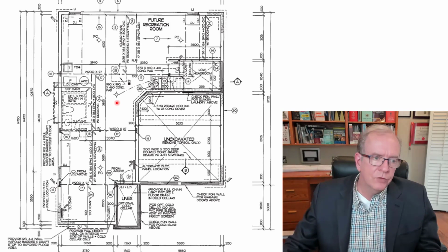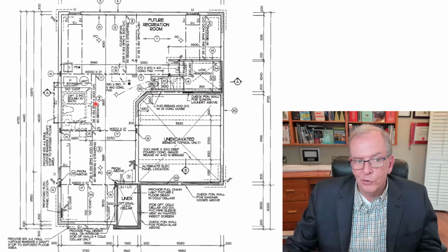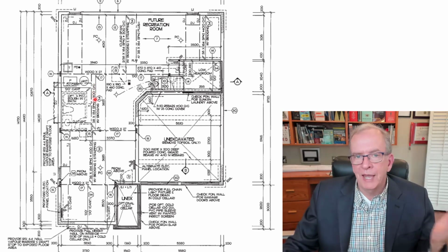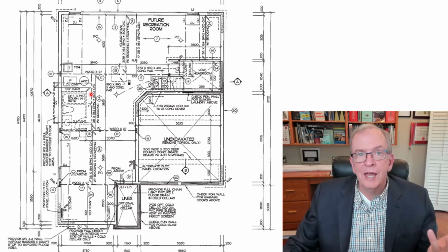And on this set of drawings here, it says 38 by 184. They're metric. If you're US based, like I've said before, I'll be using more imperial drawings as we go forward. 2 by 8 spruce, number 2. That's basically what kind of lumber. What do you use in your area that's popular, but it's designed by strength? And this would have been the same as saying 12 inches on center, even though it's not exactly the same. We always frame in Canada. Doesn't matter, our building code is metric, so we kind of have to deal with that.